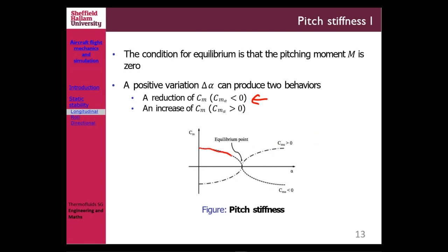So we are looking at this graph there, right? That is when Cm alpha is negative. Sometimes the graph is not really non-linear like that. Sometimes it is quite linear like that, for example. It doesn't really matter. But if you assess your aircraft aerodynamics, later on you will see that Cm alpha sometimes goes like that, right?